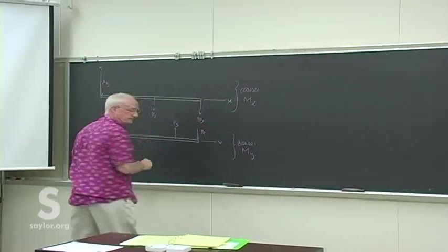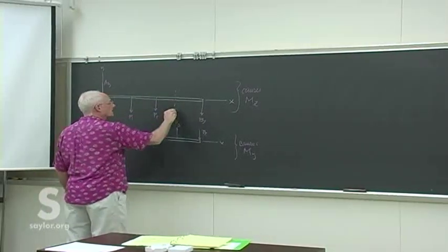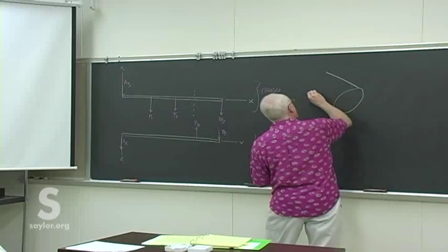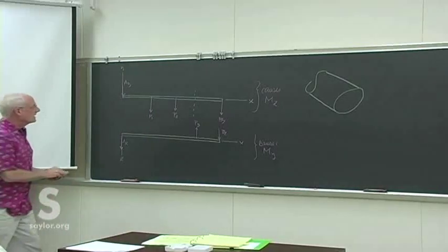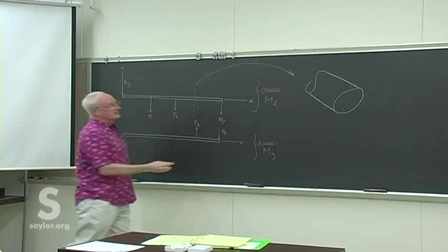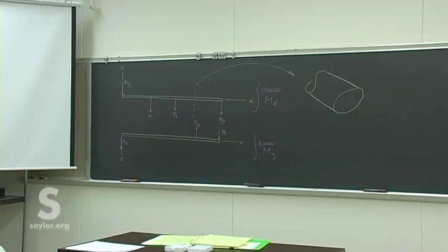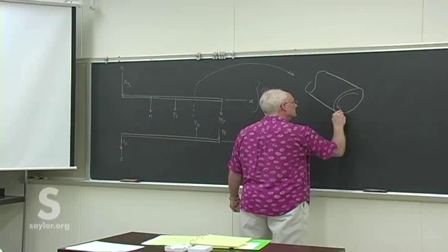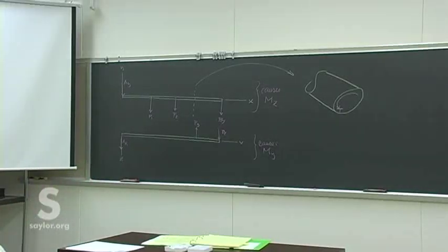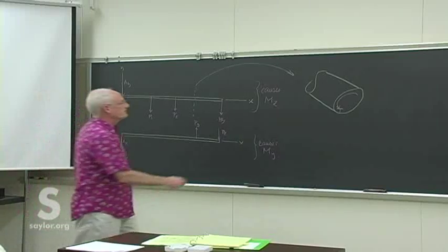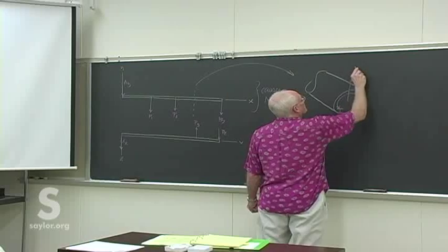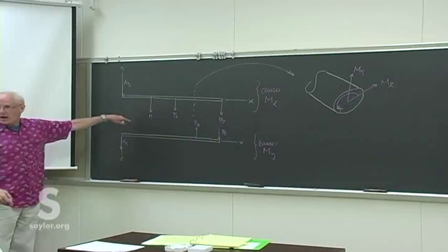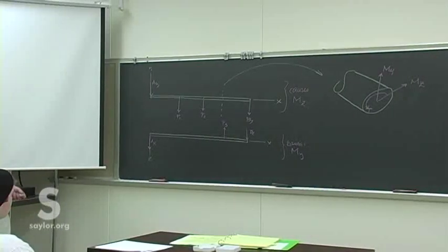So if we look at some arbitrary cross-section somewhere through the beam, look at it in some kind of perspective. So we've got some type of another one of our arbitrary cuts through these things. Don't forget we've got those torsional loads there, so we're going to see some kind of net torsion in this material, the internal forces. But then there's also going to be some net moment in the y direction and some net moment in the z direction, depending upon how all these add up, what all the distances are, all those other things that we've done for problems like that.